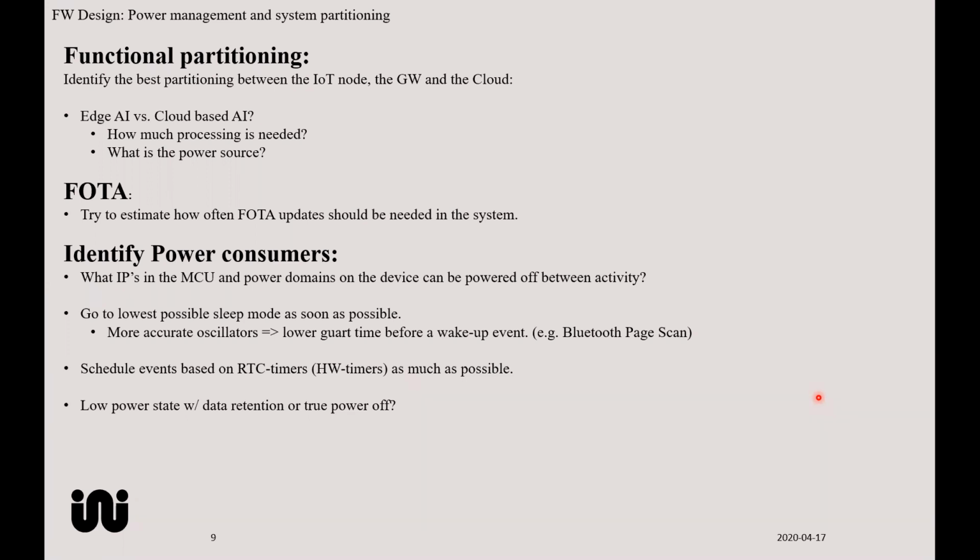If you can go into hibernation mode instead, storing the register states in RAM and keeping the DRAMs in self-refresh, and power off power to the CPU and the cores and everything else, then you will save a lot of power compared to having the system running in low power mode. But this is typically for systems where hibernation is possible. This is, I would say, not realistic for state machines or real-time OSs.